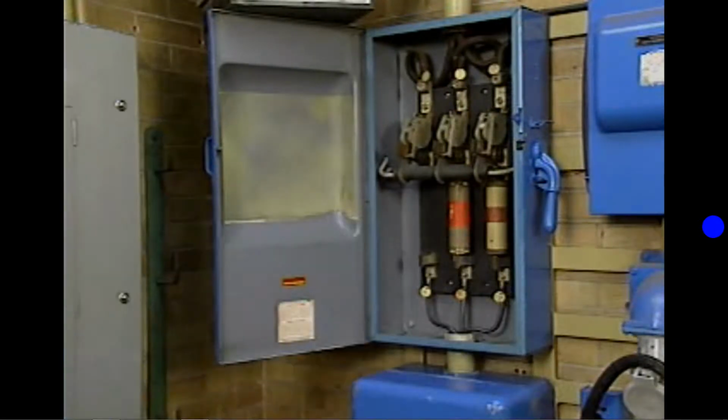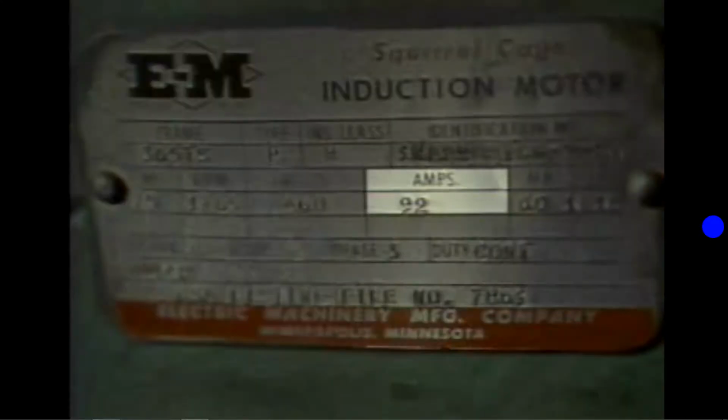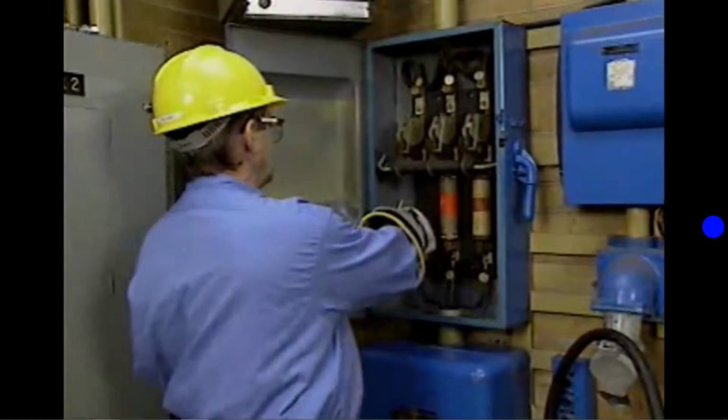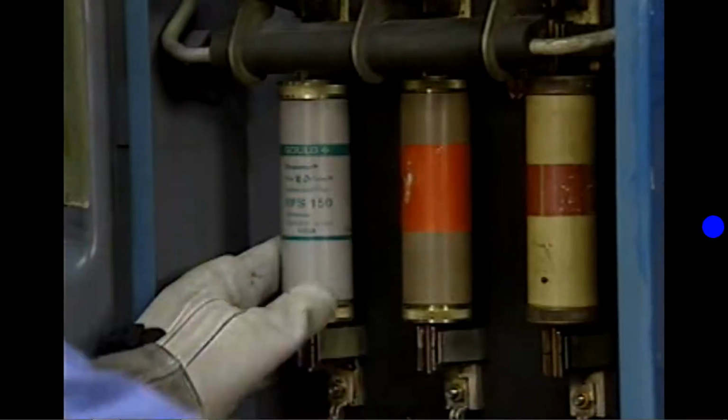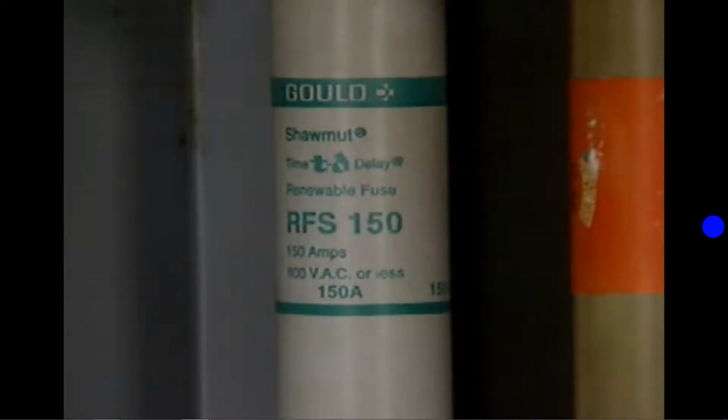Well, there's a rule of thumb that you can use as a temporary measure to identify the appropriate fuse. First, check the nameplate on the motor branch's motor to find out what the motor's running current is. In this case, it's 92 amps. Next, multiply the running current by 150%. In this example, 92 multiplied by 150%, or 1.5, is 138. So you should look for a fuse that is rated to handle 138 amps. If the exact rating is not manufactured, go to the next highest rating that is made. In this example, a 150 amp fuse is used.